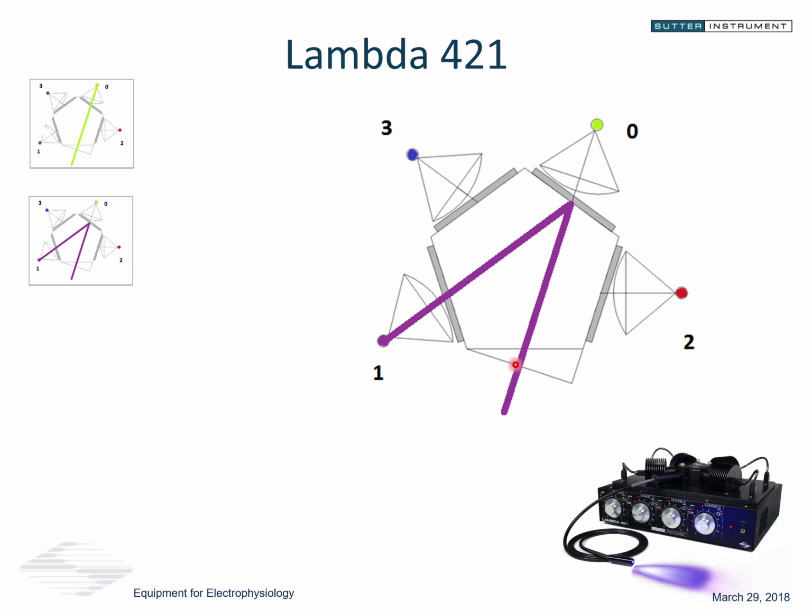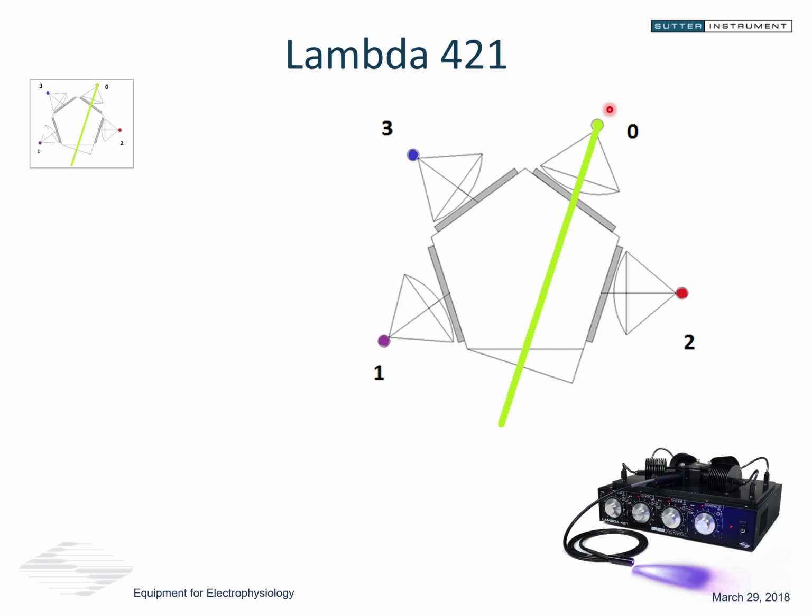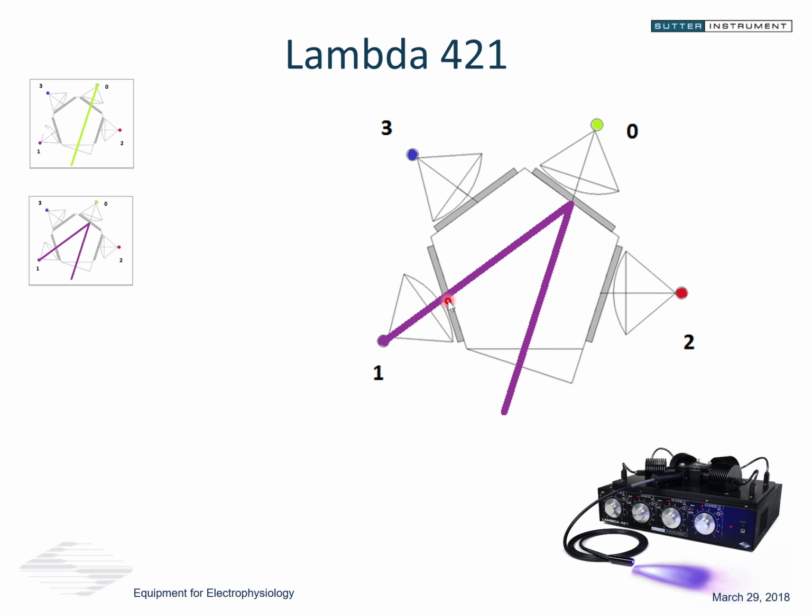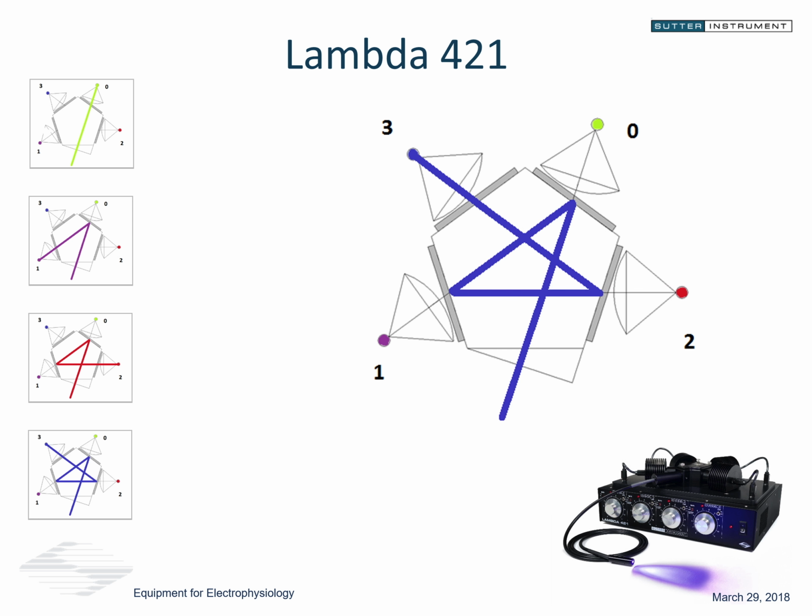So if we look at what sits in front of the first LED in this position, this is actually a bandpass filter that matches the spectral characteristics of the first LED, so that only the wavelengths of this LED are allowed to pass through that filter, and all other wavelengths will reflect. So what that enables us to do is bounce the second LED off of that filter, and in turn bounce the third LED off of those 2 filters, and in turn bounce the fourth LED off of those 3 filters, and all sent to the output. So it's all reflection based as opposed to a dichroic ladder, which runs the signals through the filters.